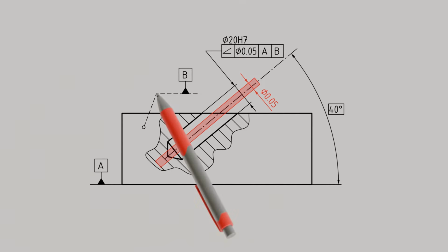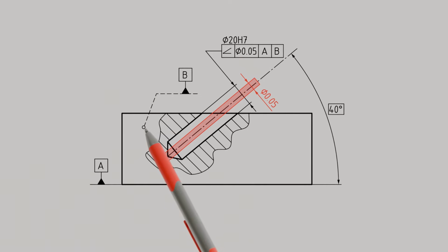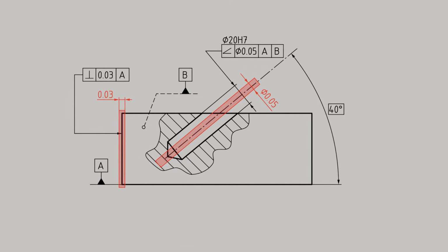The dashed leader line of datum B and the open reference point indicate that the non-visible rear surface of the part is being referenced as the datum. Note that angularity as a positional tolerance always includes the form tolerance of flatness or straightness. Because the tolerance zone is defined by two parallel planes or by a tolerance cylinder, the flatness or straightness of a toleranced feature cannot deviate more than what is permitted by the angularity tolerance.